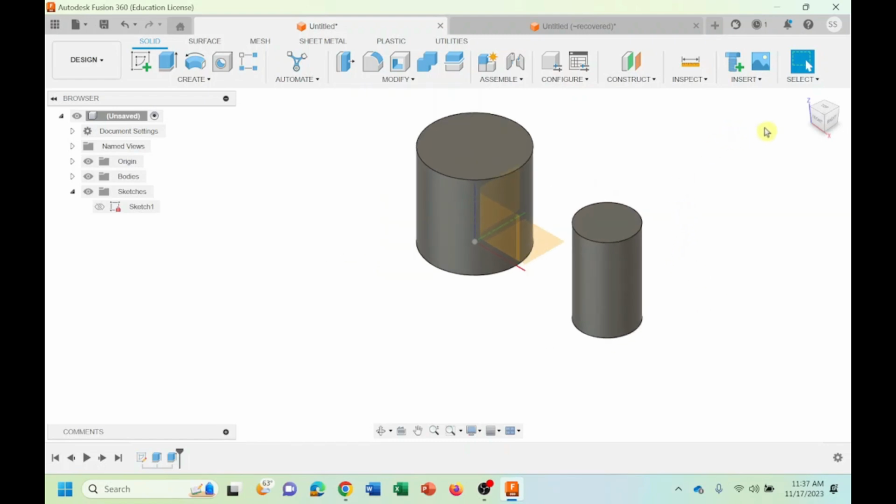The second one changed too, and that means my design is a solid design because I used some features that are able to define these two to each other. So the bottom line is follow the mindset that we had at the two-dimensional level, which makes everything constrained and defines relationships between the different objects.